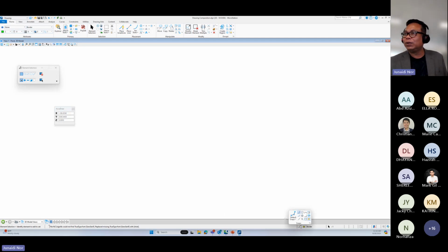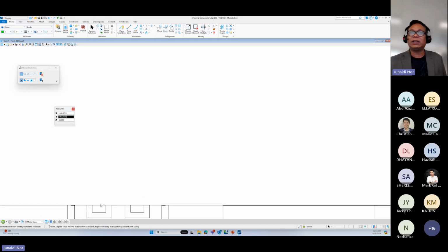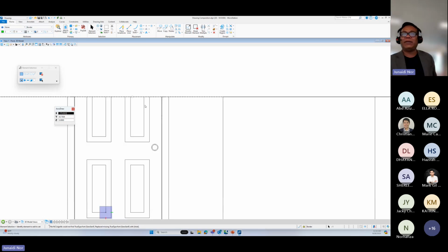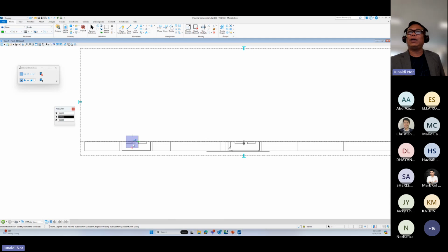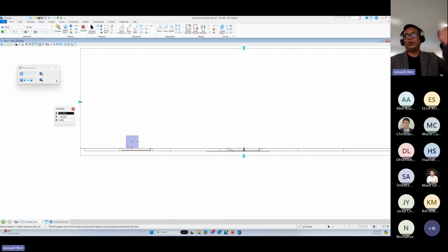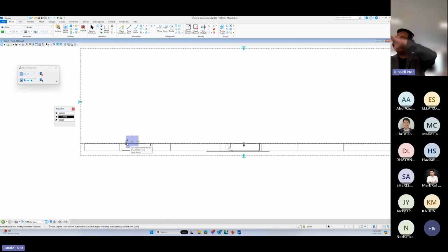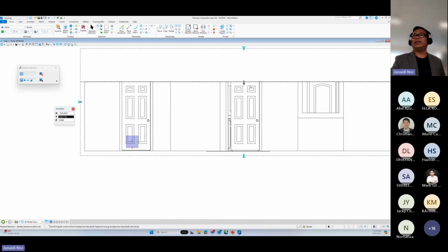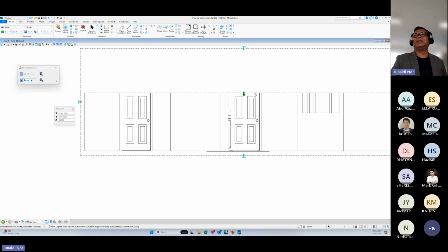Let's say this is my reference point. I change it to, maybe, the end point here. Can I select? Okay, here. When you snap, don't forget to press O. So now this is my 0 level, the surface. Then everything below this is underground. So in the project, you should know your height level. If you don't have it, you can just play with it temporarily. Okay, I go back to the top.